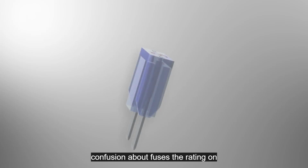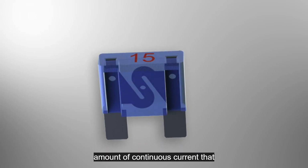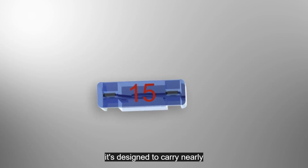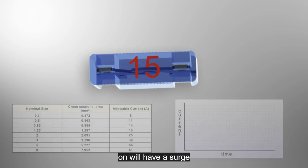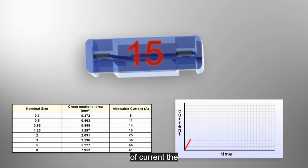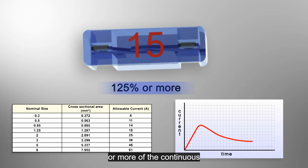There is always some confusion about fuses. The rating on the fuse is not the amount of continuous current that it's designed to carry. Nearly all electrical components, when turned on, will have a surge of current. The fuse needs to be capable of carrying this current surge without blowing. Normally, the fuse rating for a circuit is 125% or more of the continuous current.